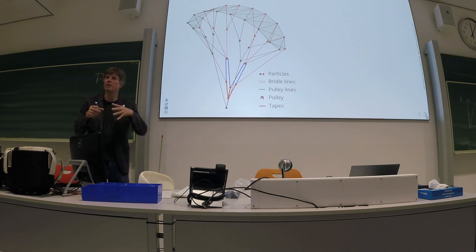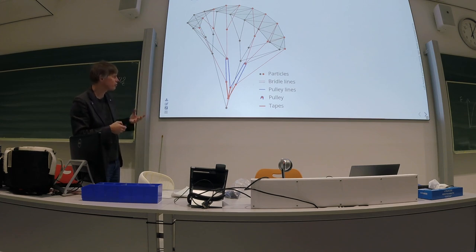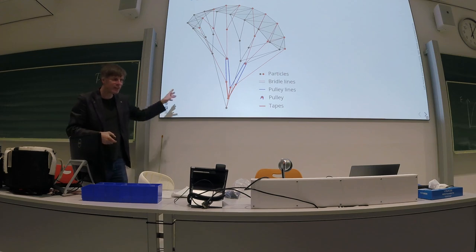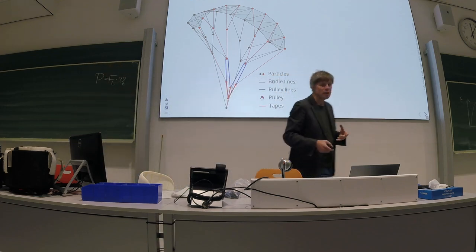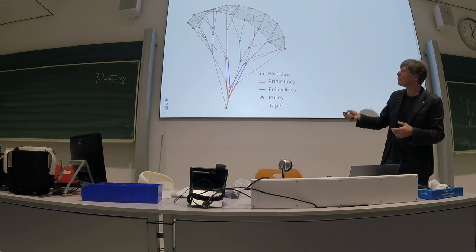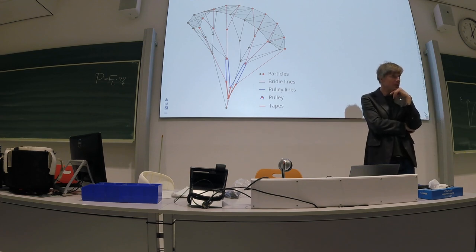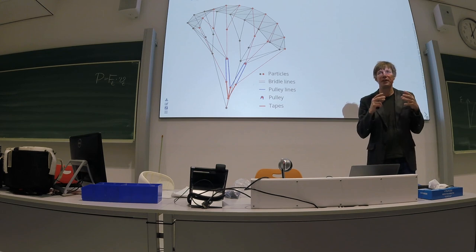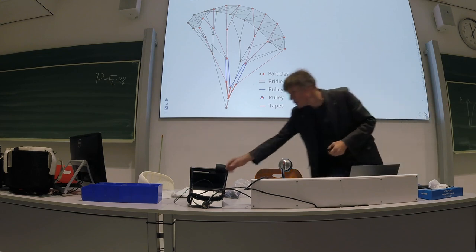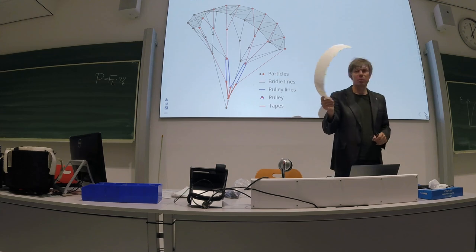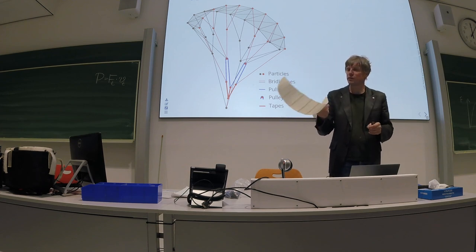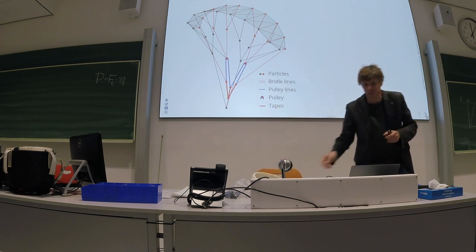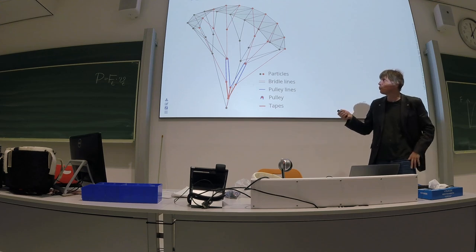We call this the KCU bridle because it's actually responsible for the actuation. What you see here is, as a side note, the fluid structure interaction model that we implemented last year with a PhD researcher. So instead of going to a finite element discretization of this wing, which you can imagine is quite complicated, we did it once, 10,000 elements you need to resolve such a wing to a sufficient degree. Instead of doing this, we went to a particle system.